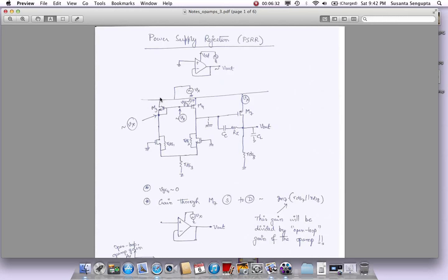Okay, so if you apply a Vx across a resistive divider circuitry, most of the Vx is going to show up here. Because this is low impedance, and this thing looking down is high impedance. That's why I've written this annotation here which says this voltage is going to be roughly equal to Vx. So if this is Vx here, at the gate, what is the VGS across this device? The VGS across this device roughly becomes 0, right? This VGS is 0 as well as this is 0.